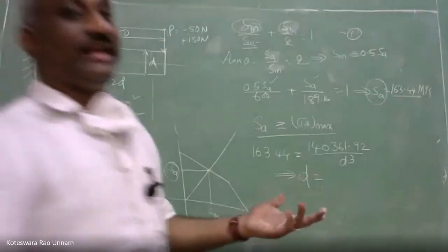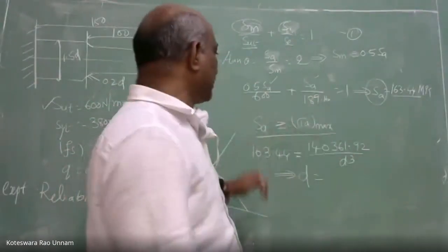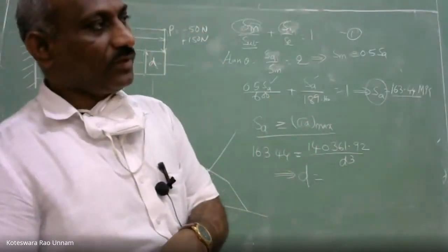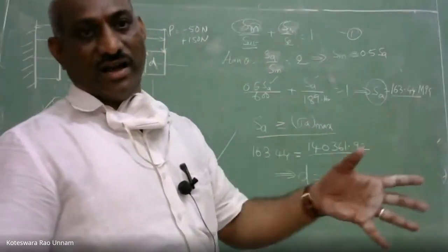Two things here. Earlier case what we did is, first we computed the D value, then we computed the sigma A max value, and then we compare SC to endurance limit, then we identify whether the life is infinite or not.